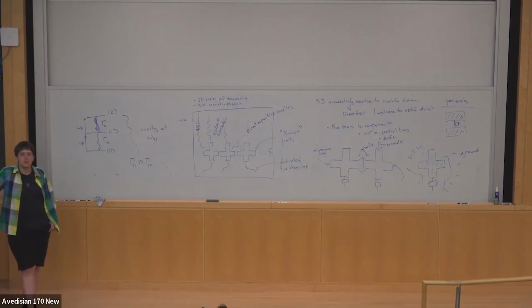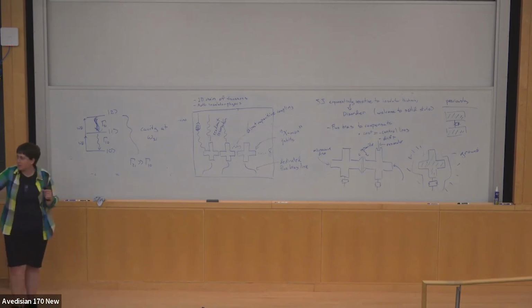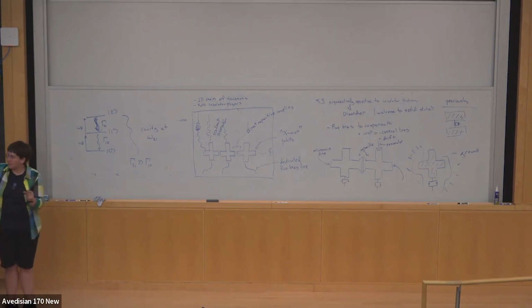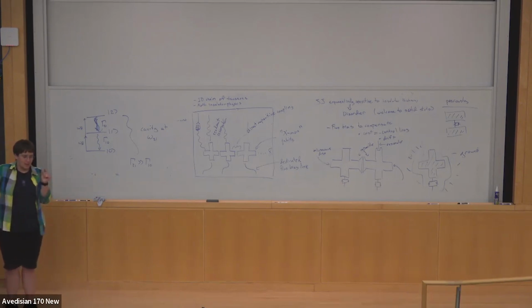Well, so this is an eternal argument between the superconducting and the semiconducting people. The semiconductor people say, my qubit is 5 nanometers in size, and so I can make 1 billion of them in one of your capacitor pads. And then if we feel like arguing, we answer back, but yes, one of your qubits takes 25 control lines, and the footprint for all of the DC voltages that you use to control that one qubit is A, bigger than our qubit, and B, blocking your ability to put any more next to the first one.